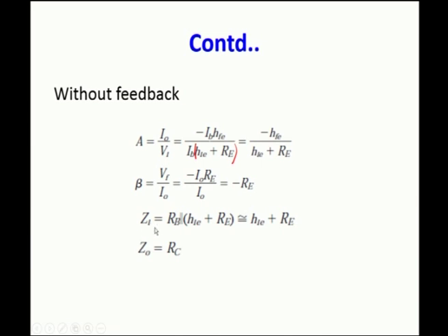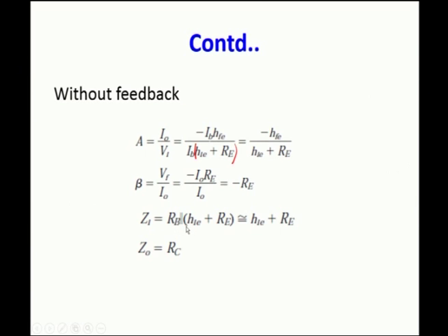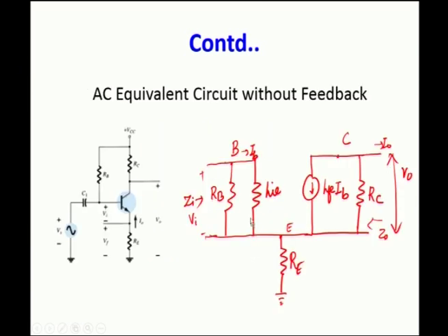So, what is the input impedance? It is RB parallel (hie plus RE).